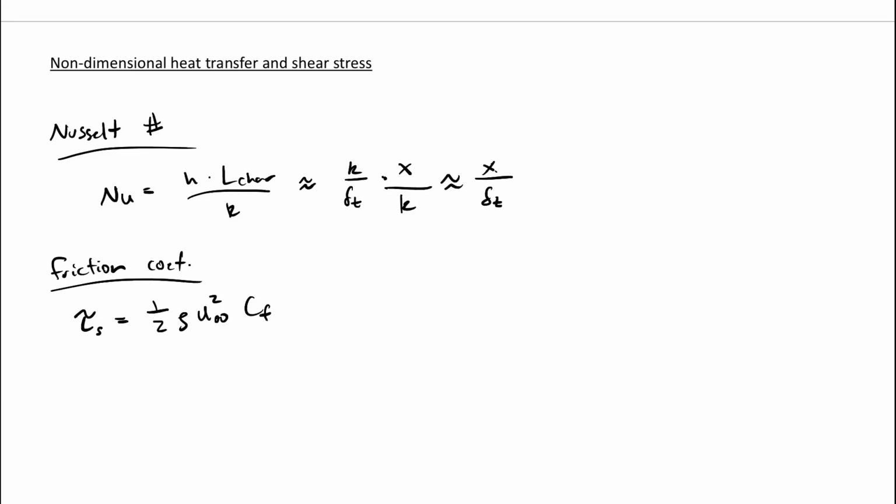But normally that's not the case. There are some other things happening, like heat dissipation due to shear. Not all of it goes to momentum. So you have this CF that's introduced. So we can rewrite this. We're going to use tau approximately equal to mu times U infinity divided by delta M. Using that definition of tau and what we just wrote out, mu U infinity over delta M is equal to 1/2 rho U infinity squared times CF. So let's solve for CF.